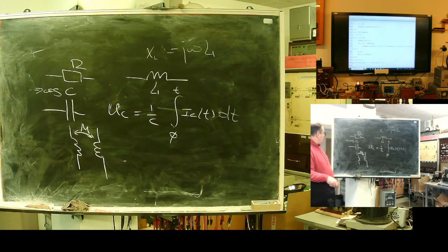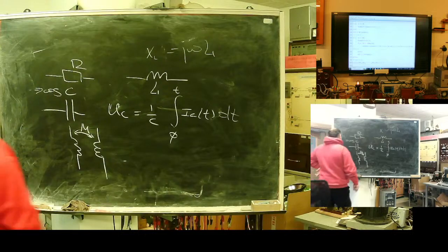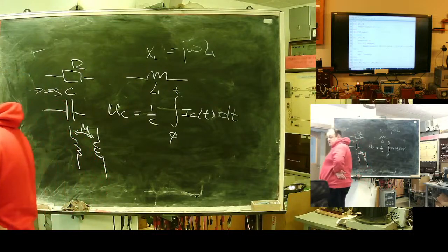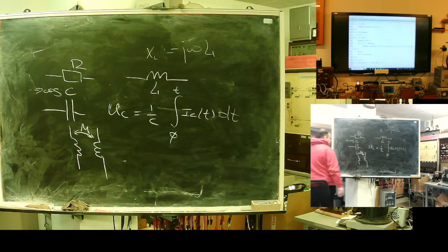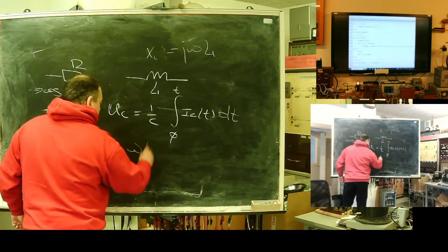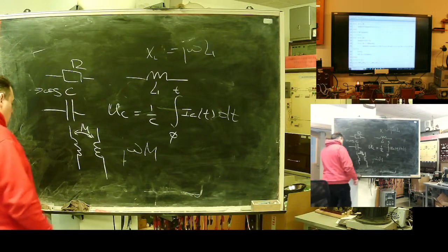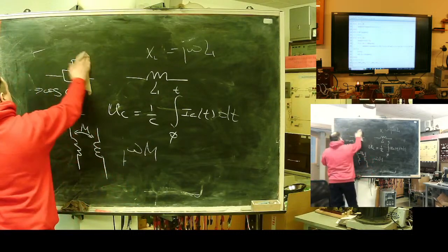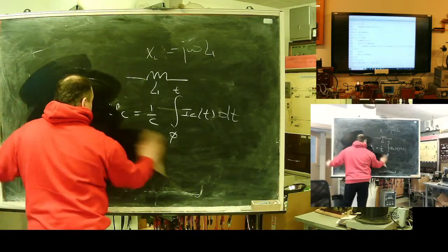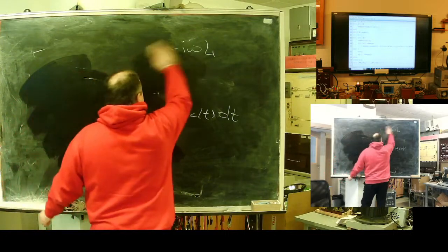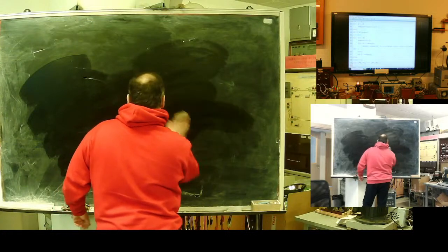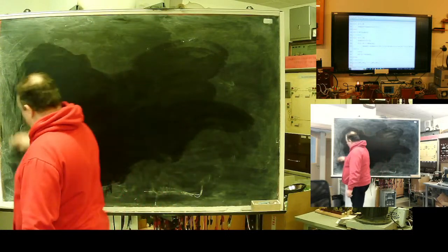What I would like to say? Yeah, mutual inductance. It has the dimension of inductance. It's also measurable in henries, millihenries, and so on. And it will appear as omega M, but not as a branch resistance, but as a mutual resistance between branches.